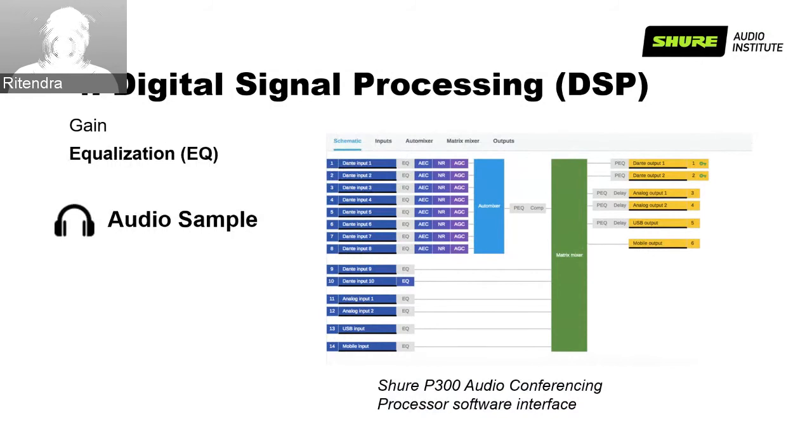Equalization, or EQ, is useful for reducing and boosting frequencies in a given channel or mix. I'll give you a few tips for best results. Please keep these tips in mind when EQing a signal. First, cut or reduce first. Then, if necessary, make any boosting adjustment.